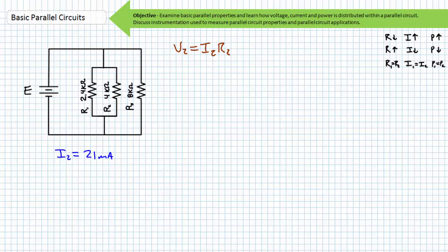What would the knowledge of the voltage across R2 gain me? Aha! A couple of you might be slapping your foreheads right now, but I bet your lab partner is still staring blank-eyed at the screen and drooling on themselves. Yes, knowing the value of the voltage across R2, I am immediately aware that this same voltage drop must appear across both R1 and R3, because voltage across elements hooked in a parallel relationship is the same, and those voltage drops must have come from an equivalent voltage rise. The rest of the problem is not a problem anymore, it's just a duck shoot.